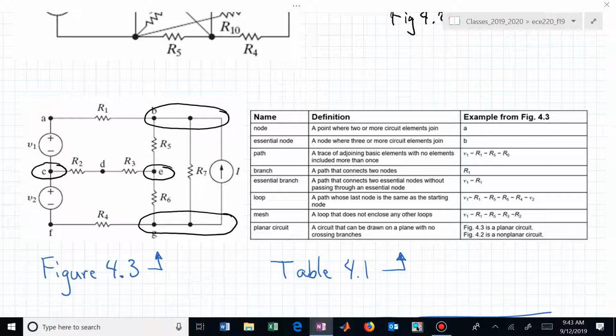So the dot to the right of B and G is redundant, but it's telling you those wires are connected. But you could glob all of those together. If you were soldering everything, you wouldn't want to make a soldering blob, but you could connect all of those pieces together and have one node.